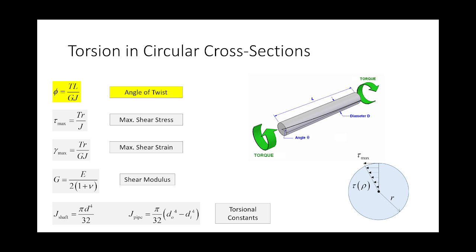However, with torsion and with things like bending, the stress changes depending upon where you look. And I think a lot of students really understand this with bending. You take an element, you bend it along the neutral axis, you get no strain or stress at all. You get compression one way, tension along the other way, right? So you bend the beam, smiley face bending, it's compression on the top, tension on the bottom, zero bending stress and strain along the centroid. Torsion is where in mechanics of materials you first start learning about how stresses can change dependent upon where you look. If I take a circular element and I twist it, it rotates, it twists, right?